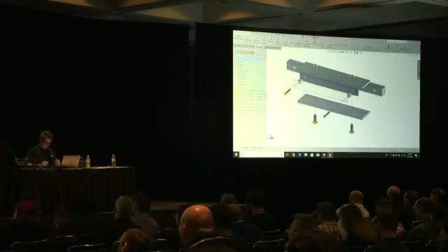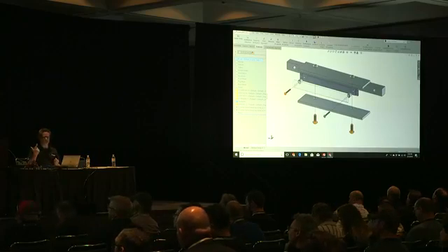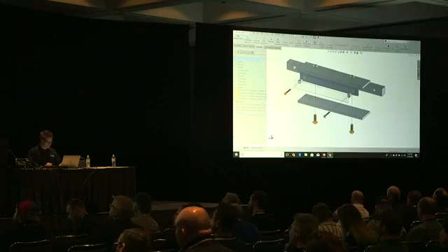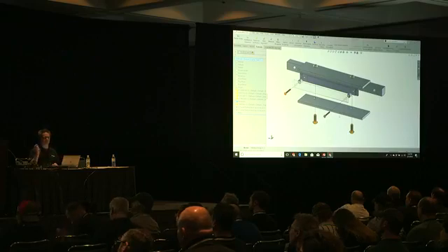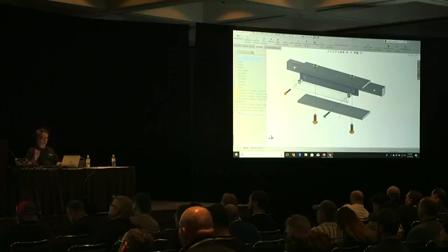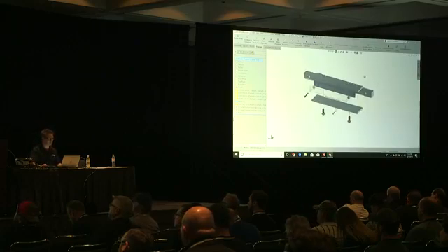It's okay. One of the things that I do when I leave a file, when I'm done with it, hold down the Control key. Number 7 is isometric. B is rebuild. S is save. W is close the window. So hold down Control 7, B, W, S, or BSW. You want to save it before you close it.